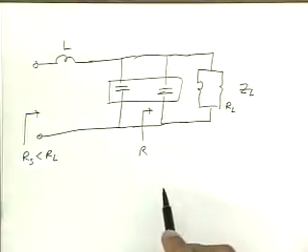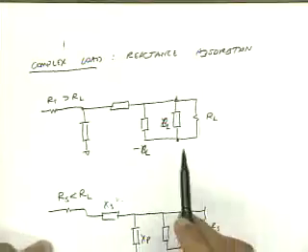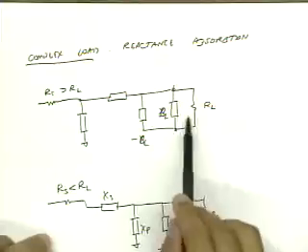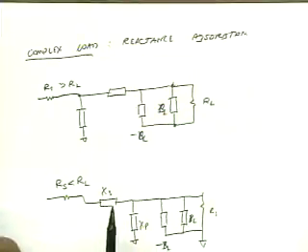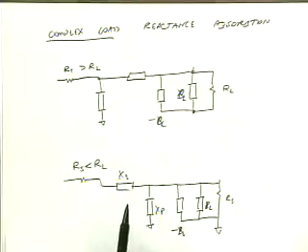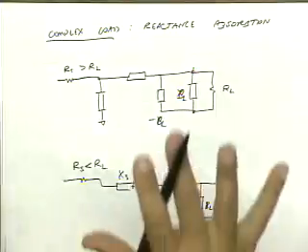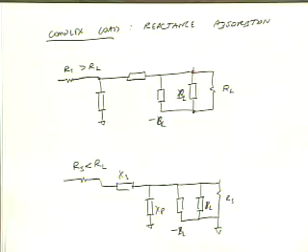So that's why we call it reactance absorption, because a lot of times we can absorb the complex part of our load and source into the matching network itself. So even though the matching networks that we've discussed up to now, all the design equations were for real loads and real sources, you can see that it very simply generalizes to complex source and complex load. Okay? Any questions about that?